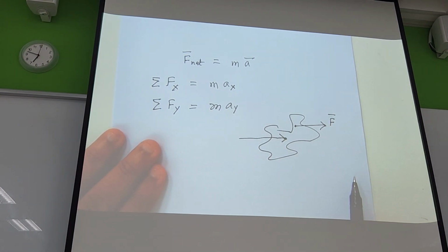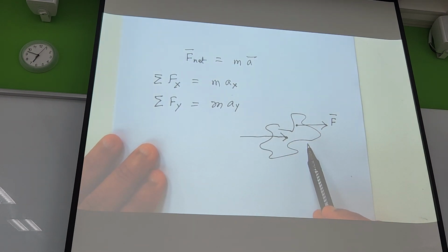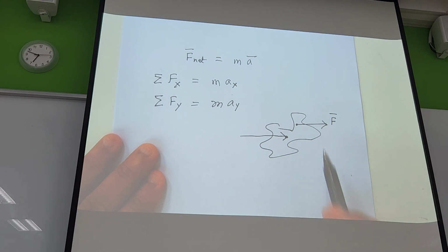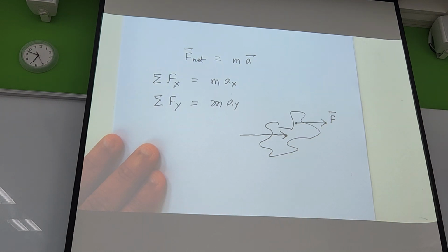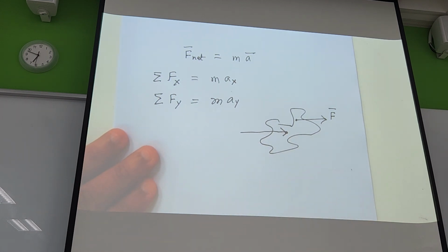So then these two equations are not valid in this case. So these two equations are valid only when the force is acting at the mass center of the system. But when the force is acting away from the mass center, then the moment of force or the torque will affect the movement of the system. So in that case, we write differently because the body is subjected to rotation.